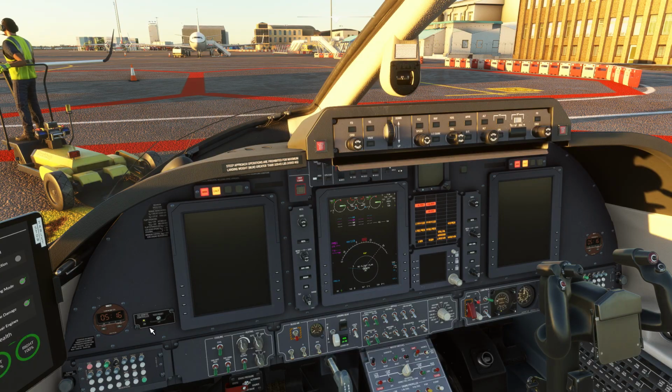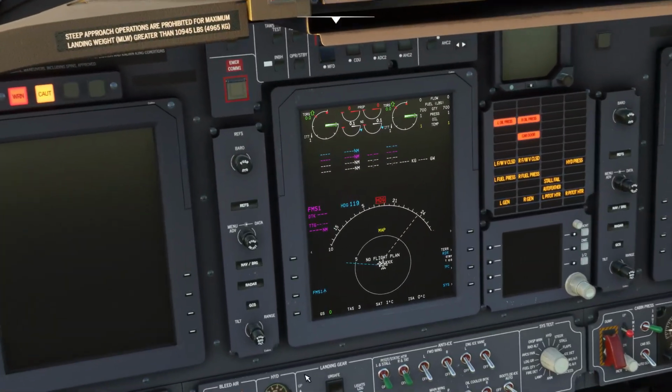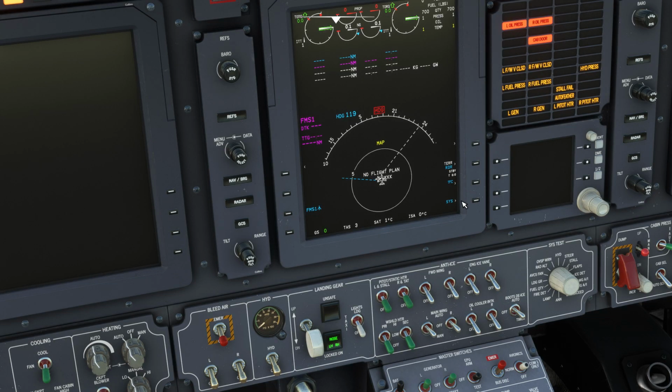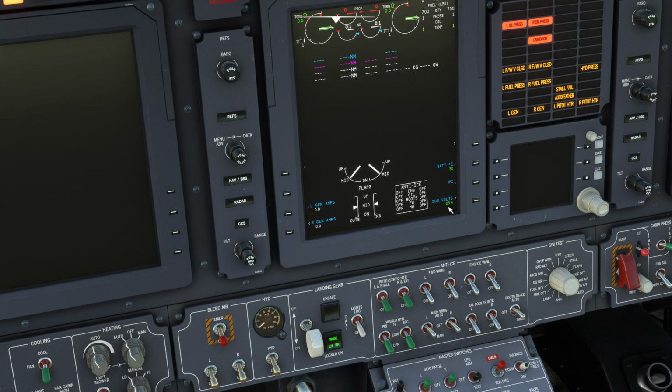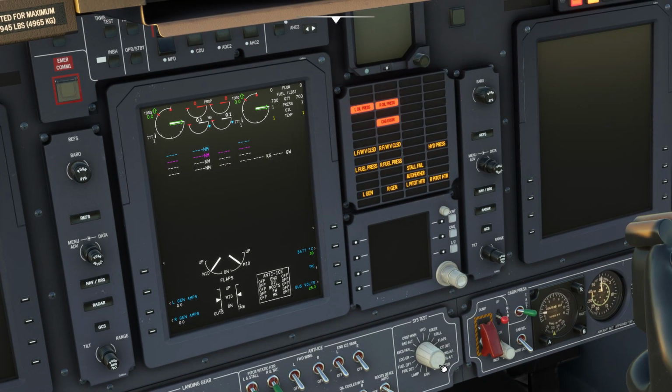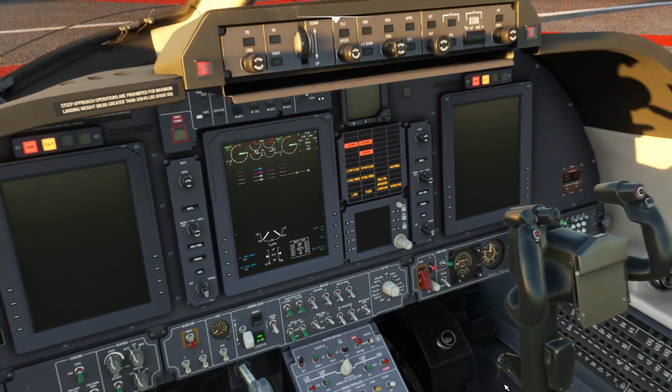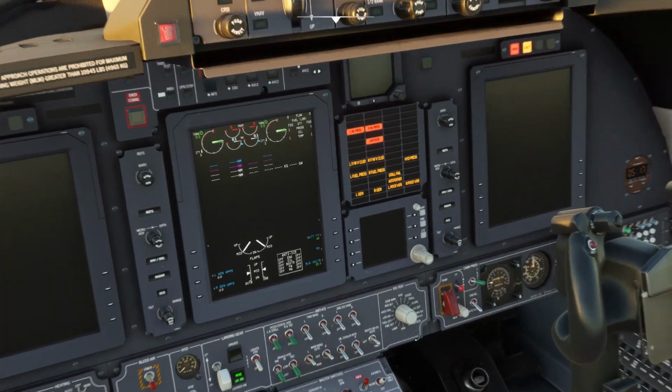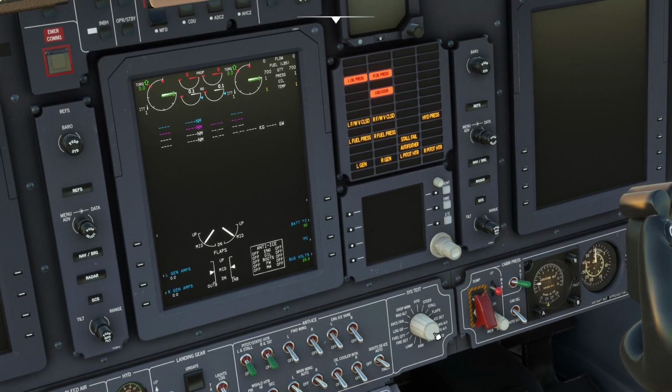Right. So battery is on. Bus voltage is read through here. Right soft 4 button. Click. Bus voltage here 25, which is fine. Now our generators are off. The engines are off, obviously. Annunciator panel. So we go to this knob, we move the arrow on that knob to annunciator, and you press the knob. That's your annunciator test, which is working. Engine ice detector.